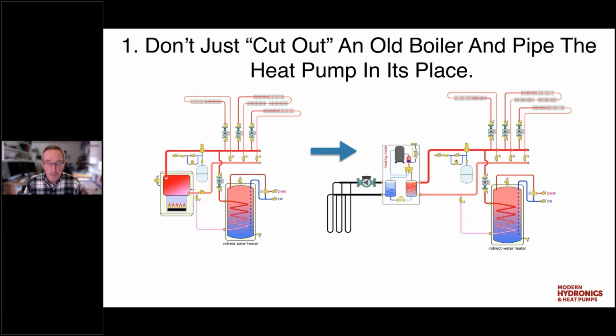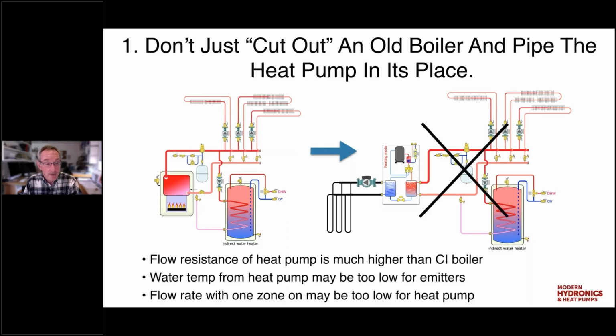Again, the water temperature requirements of the heat emitters, the flow, especially if there's only one zone operating, these are all going to ultimately reflect back on, can the heat pump provide that performance? And when it's very high temperature water that's required at design load, today's heat pumps really can't provide those temperatures. So we don't want to do that.